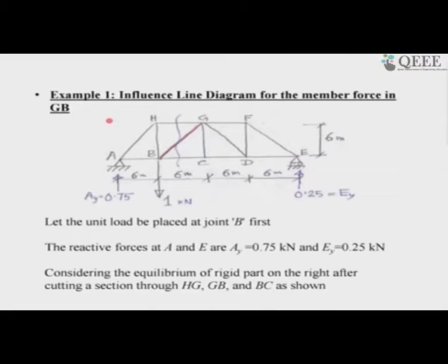So, now let us take an example of a truss. What should I do with the truss? We will examine how the member forces change as a unit load moves onto the floor, and we have already agreed that ultimately that unit load has to cross the node points, and while crossing the node point it has a unit load. So, let me examine at each of the node points, through the load transfer mechanism, that the unit load is moving onto the bottom chord, suppose.